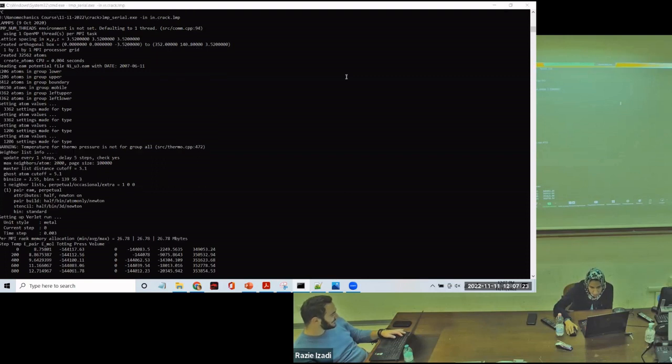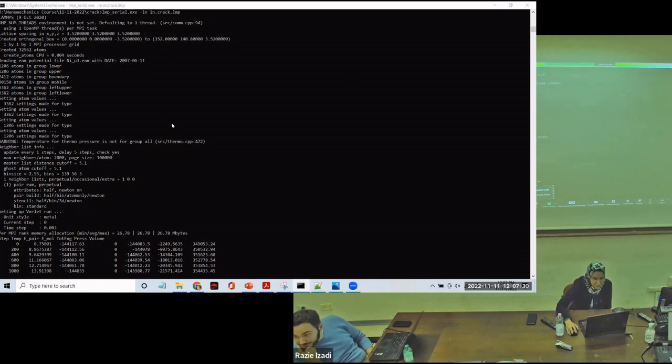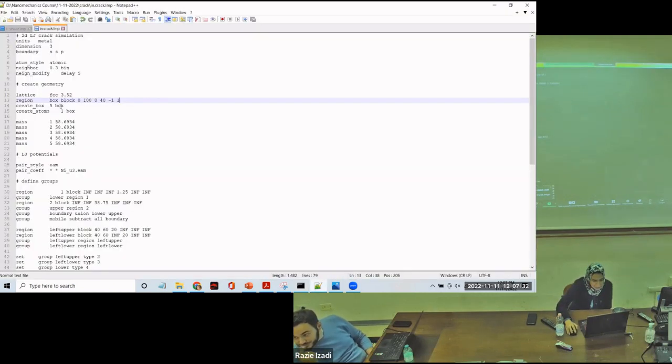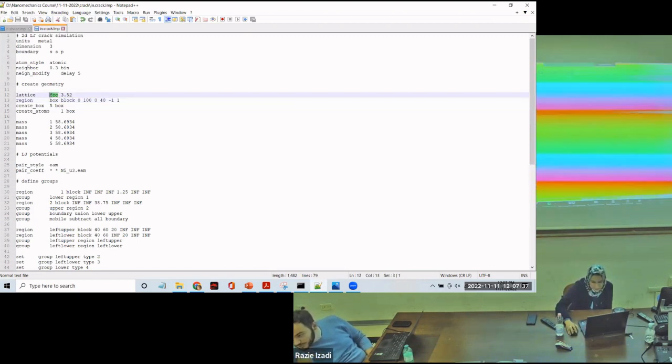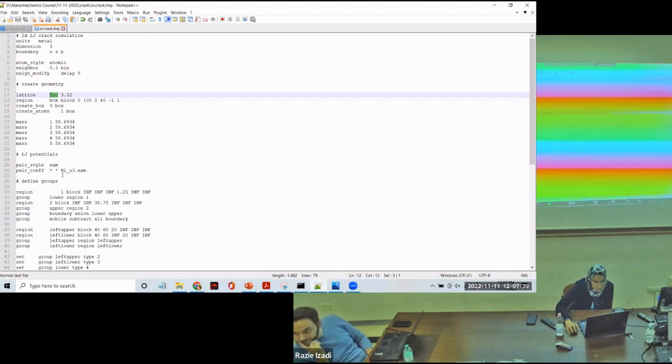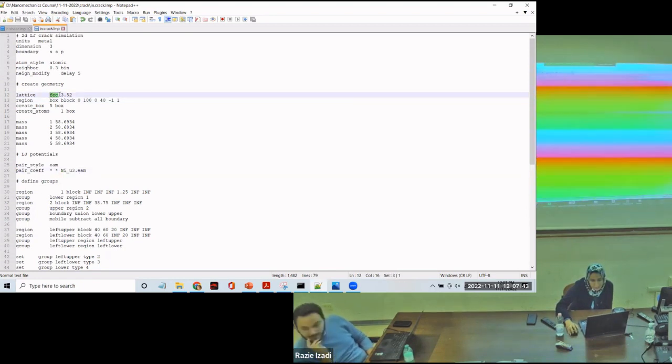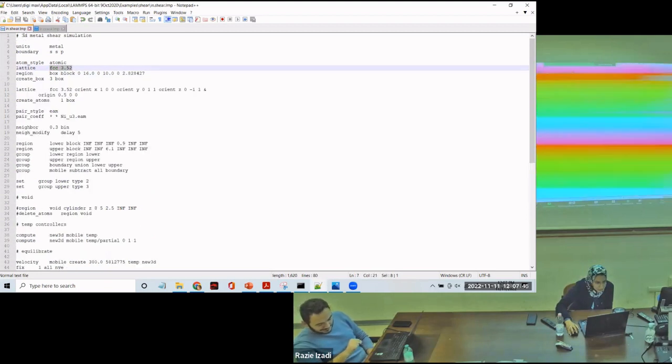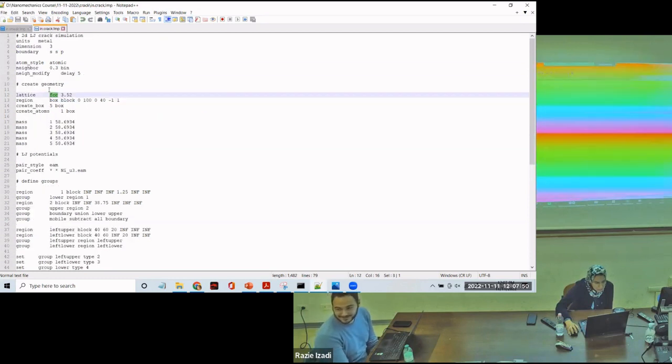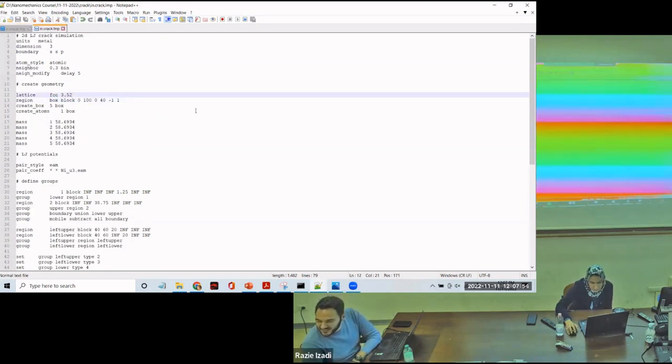So, Marco, you should change... what was the very last change? The very last change was that we changed the lattice; the first version wasn't FCC, okay? But when we use nickel, the compatible lattice structure is FCC, okay? I use the lattice FCC 3.52, and I put it here in front of the lattice because this one is compatible.